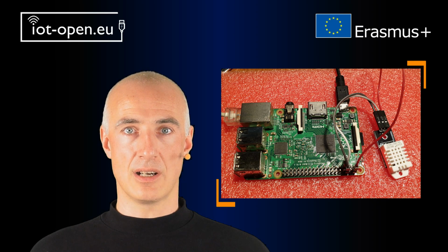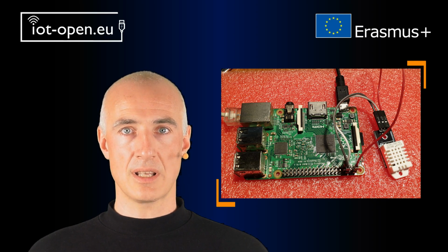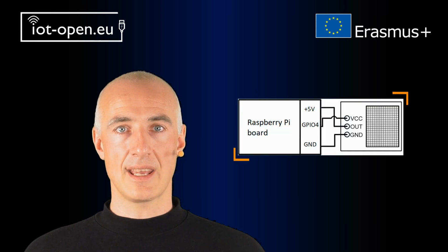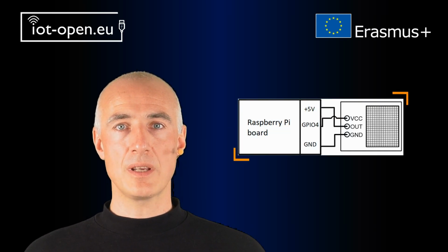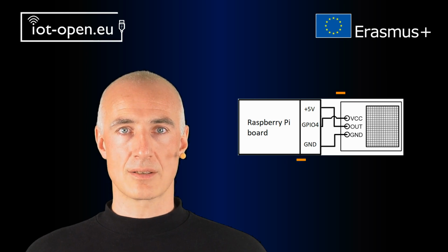The output of the humidity sensor is usually a single analog value. Example IoT applications are monitoring of a humidor, greenhouse temperature and humidity, agricultural environment, but also monitoring critical air conditions in an art gallery or museum. In a similar way to the previous examples, we use GPIO4 to connect the sensor to our RPI. This sensor uses a more complex communication protocol, and there are a number of Python libraries enabling its use, similar to those written in C++ for Arduino boards.